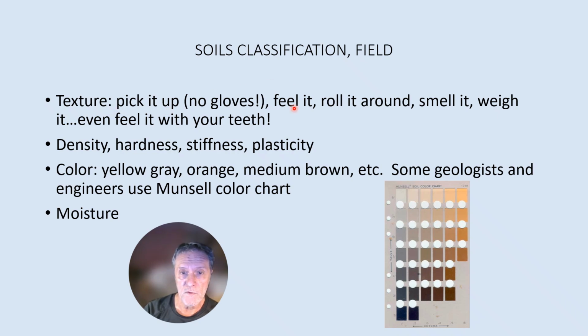You can feel it, roll it, smell it. Smelling, you can detect organic odors or other odors. Put a little bit of it between your teeth. If it's gritty, it's got sand in it. If it's not gritty, it's a silt or a clay. You can determine density and hardness, general relative stiffness, plasticity, whether it's clay. If it's a clay, it can be plastic. If it's a sand, it's not plastic.